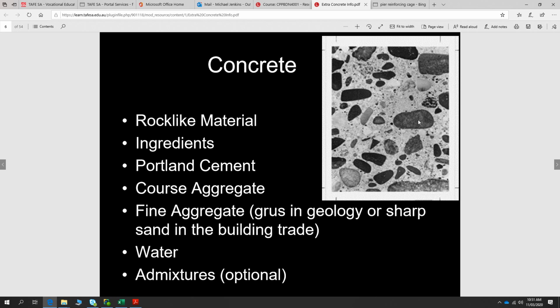Or if you want various different colours and finishes, then you want to choose your admixtures for that as well. If ever you're going to be working with something specific, to create a specific result, the best people to speak to are your concrete suppliers. So we've got probably either Hallett's or Direct Mix, really. Or Boral in Adelaide as well. Premix, yeah. So speak to them about what you're wanting to achieve.